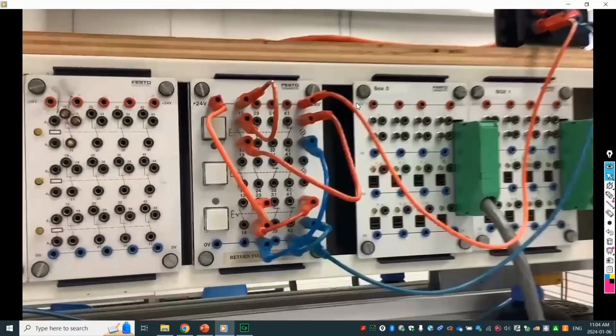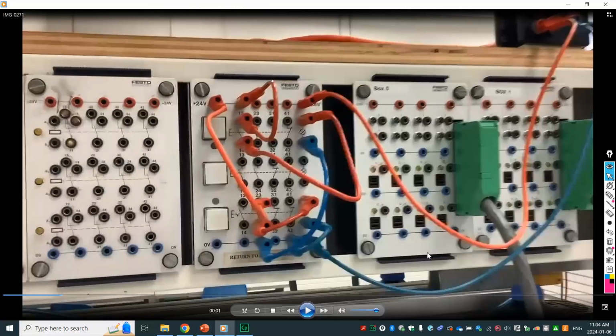All right. So over here I'm showing you two very simple circuits from the Festo trainer. I basically wired two buttons to control two different lights. As you can see here, this is the 24 volt power supply, and the blue cable is the 0 volt. So I get 24 into this button, which is normally open, and then go across the button and connect to a light bulb. The light bulb is actually just behind this button cap, inside there. Then from there, it connects to the 0 volt.